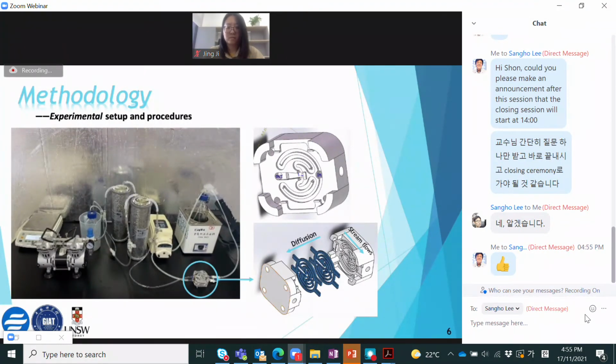During the PV test, the TCM wastewater will be kept at a certain temperature and then pumped through the membrane module and then go back to the reservoir. And inside the module, the mixture solution will be forced to travel all the way through this long and curvy channel and in constant contact with the membrane pressed on top.